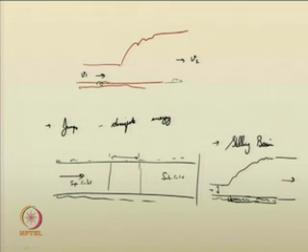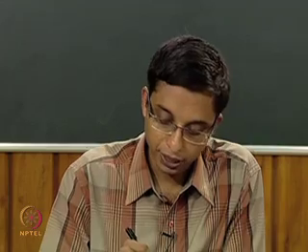This particular reach of the channel is called a stilling basin. Why? Because it is a basin that provides the provision for hydraulic jump.